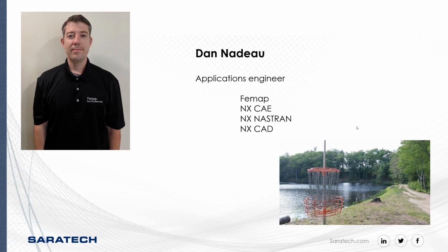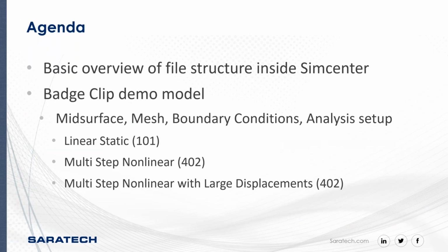So the agenda today. I'm going to give you a brief overview of the file structure inside Simcenter. I'm going to give you a demo model of a badge clip. Inside that demo model, I'm going to create a mid-surface. I'm going to apply mesh, boundary conditions, and go through analysis setup. And the analyses that I'm going to solve are linear statics, multi-step nonlinear 402, and multi-step nonlinear 402 with large displacements toggled on to include those nonlinear effects.